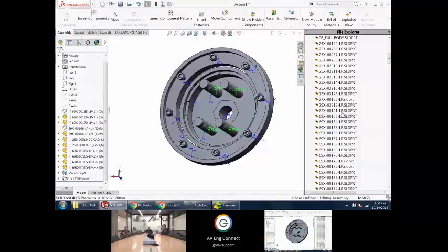Okay, just a few more parts into this assembly. Before I go into the other parts here, though, all this stuff that I've got here, remember I was talking about if things are free to move, it takes longer to solve. All of these are free to move because I didn't lock rotation on a single one. Somebody asked me this earlier, do you want to lock rotation on all of those? An easier way is just to select everything that's got a minus in front of it and hit Fix.